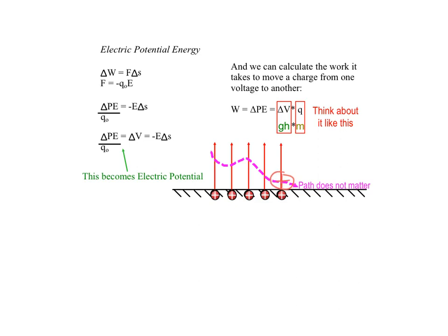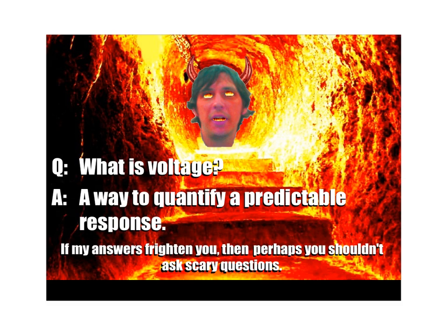Just like if we talk about work to lift something, the specific direction we talk about is lift it up, which is against the gravitational field, and that's going to tell you how much work you've done on a specific charge. So that's the analog. As we think about this voltage thing, it's just position within a field. And so if we understand what voltage we're at and what voltage we're going to wind up in, that's going to tell us about the work that gets done on the charge, which is going to tell us about its change in energy. And ultimately, that can tell us things like how fast the charge will be moving, or how much energy it gained.